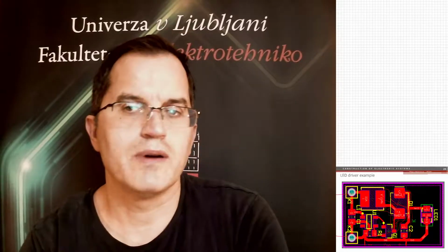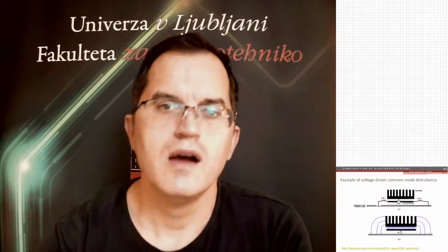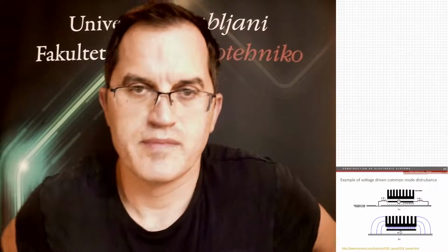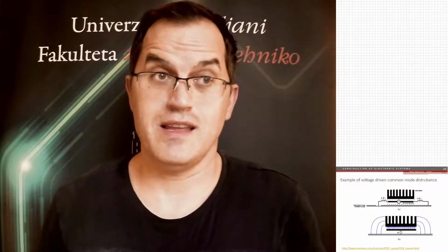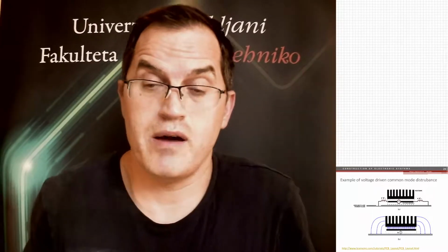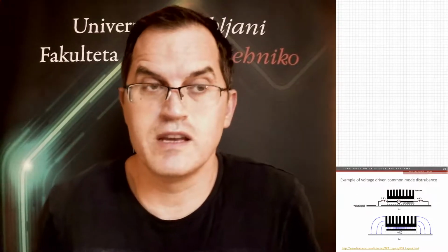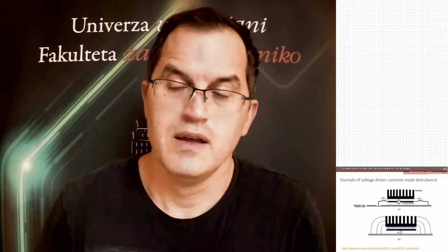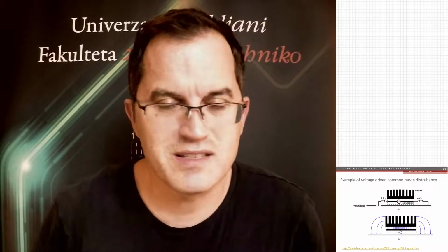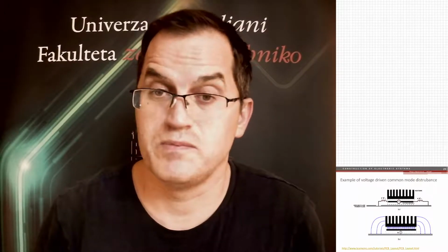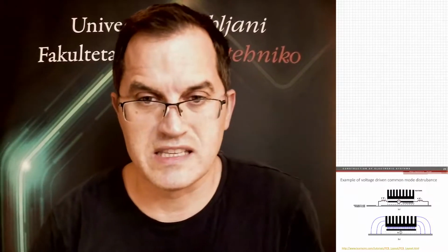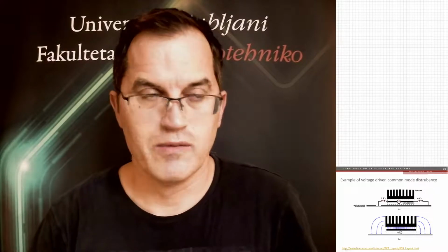So let me wrap up this lecture just by a few other slides. One of the problems with the switching of the transistors is also that they heat up quite easily because they are high power elements. They are switching high currents and voltages. Therefore, you have to cool them down with some heat sinks. And heat sinks, well, they are a nasty thing because the heat sink is increasing the area of these devices.